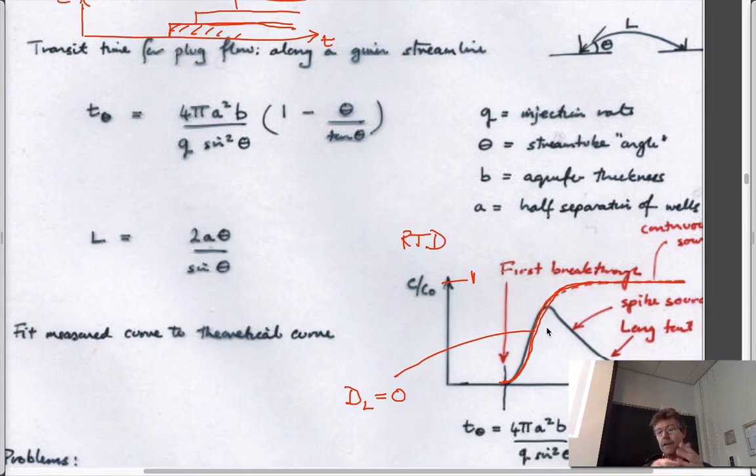It's quite apparent, I think, in this 2-well case, but it's also kind of apparent in the single well case, because you think about it, if you look at flow within a single well, it has to flow in this. So this is the stream tube that is flowing out from the well to get to the exterior. So if you look at the velocities as you went out from this particular well bore, what would the advective velocities look like as you go laterally outwards?